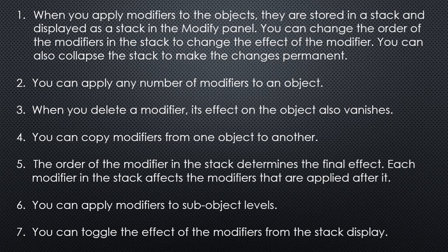Second, you can apply any number of modifiers to an object. Third, when you delete a modifier, its effect on the objects also vanishes. Fourth, you can copy modifiers from an object to another. Fifth, the order of the modifier in the stack determines the final effect. Each modifier in the stack affects the modifiers that are applied after it.